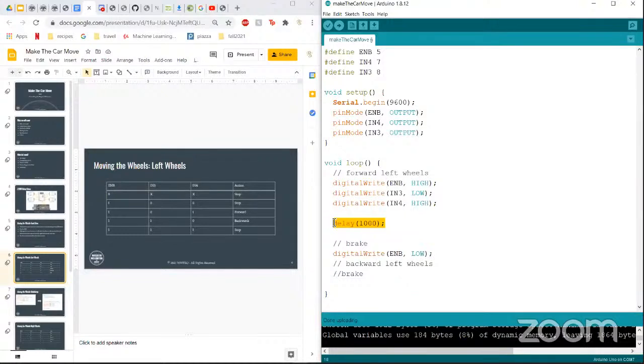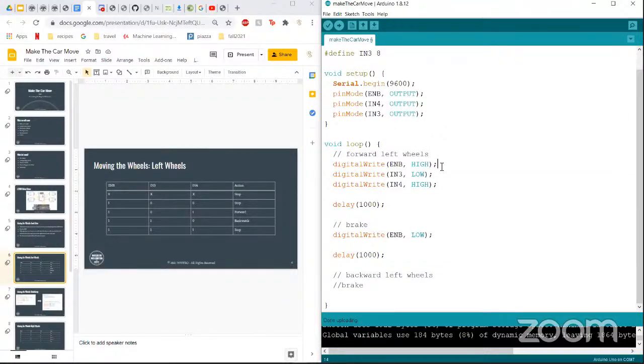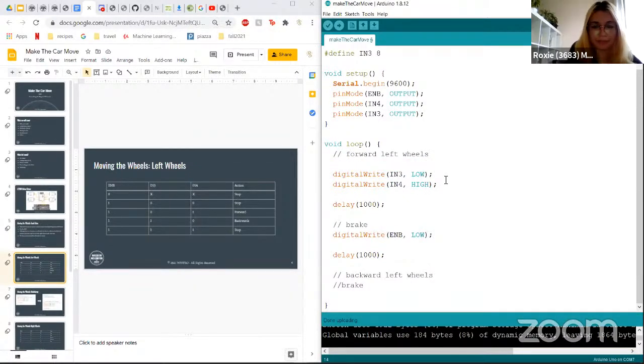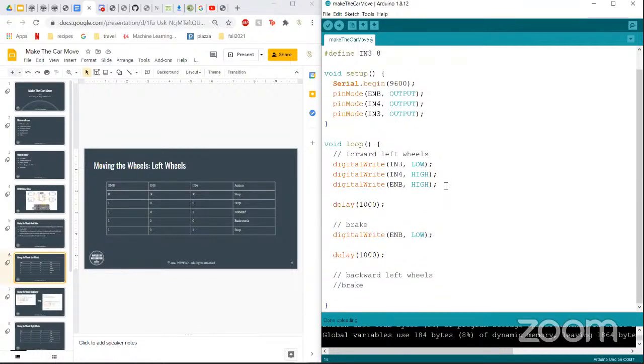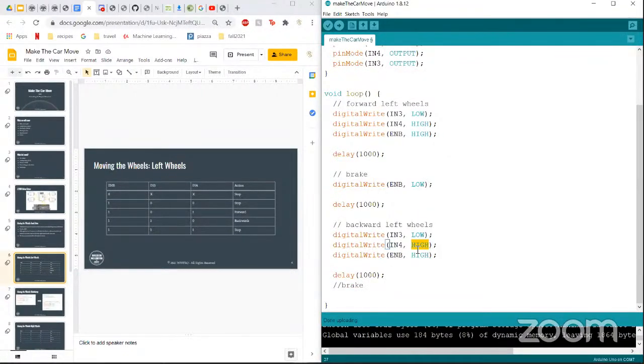And if I can offer a pro tip that doesn't totally matter here, but just as a matter of habit, if you have an enable line on a control system like this, often it's better to enable it at the end. So you would set your INs, then you would enable it, just so you don't have the funny situation if you're actually controlling a tractor and you enable it first, it'll go in whatever direction it was set for before, and then it'll figure out that you've changed direction. So here, it really won't matter. It's such a small thing. But at that job I was talking about earlier, we had a glitch on an input on reset, and it made the shovel go up about 6 inches on this microsecond glitch. So it can be dangerous in real life.